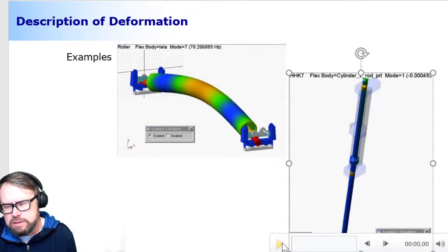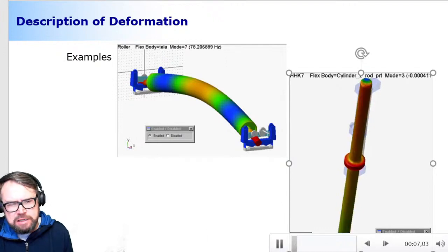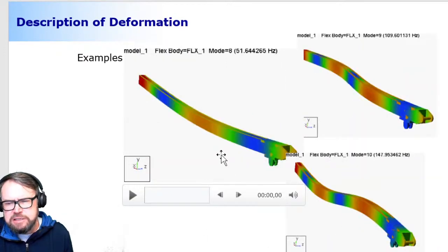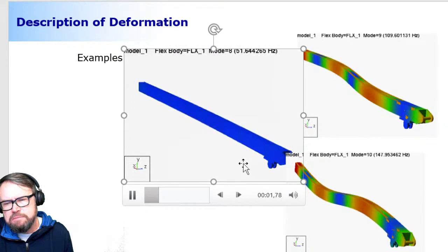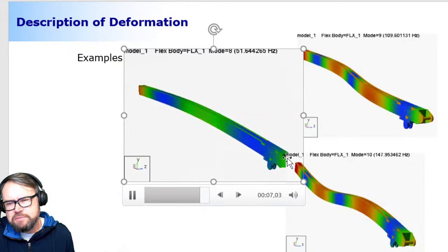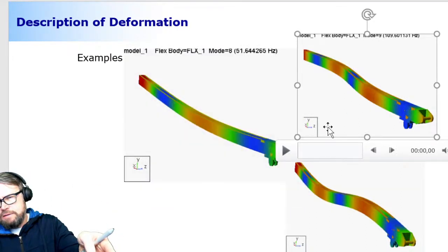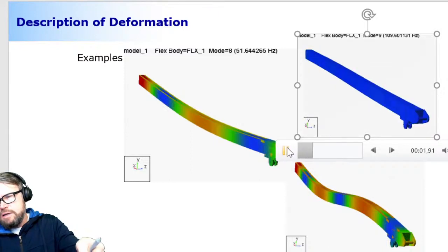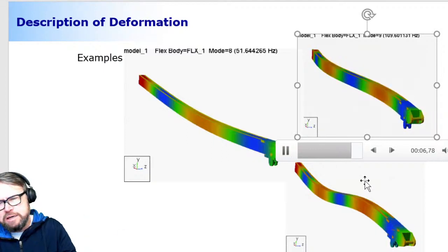Now, what I really would like to do here is explain this eigenvalue analysis to you in a bit more detail. Okay, so these are the results. I think this is the best describing. These are deformation modes of this kind of simple structure that I'm sure you know what it is. So this is a deformation in this direction, and this is a deformation in the transverse direction. So these are the ways that the structure can deform, nothing else.